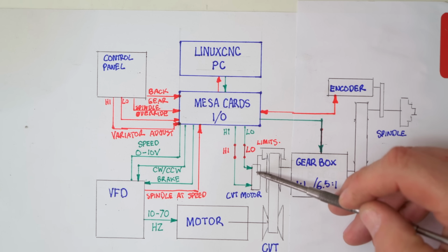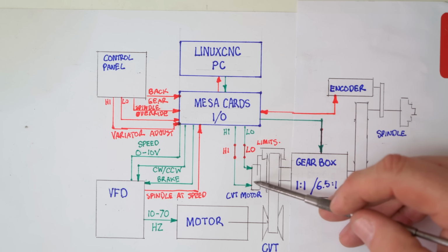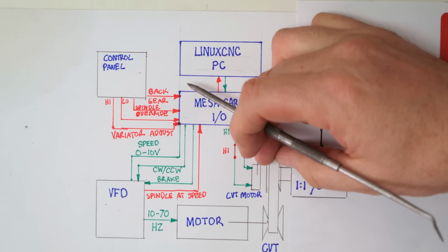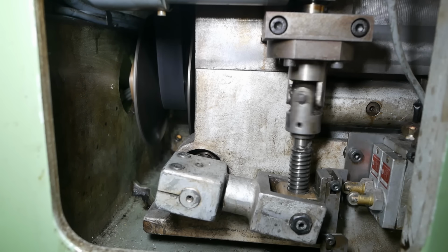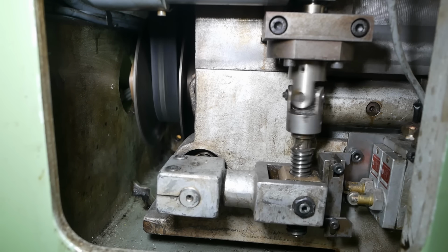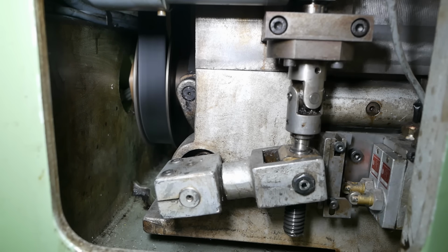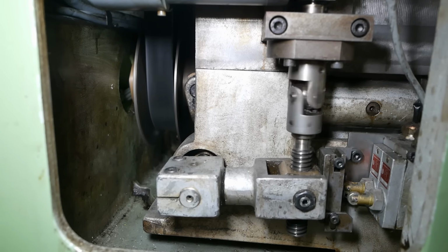Unfortunately, this three-phase motor, which turns at constant speed, is driving some gearing to squeeze it together or open it. It takes about 5 seconds to go from the lowest possible ratio to the highest possible ratio. However, the change in reduction ratio is not linear over those 5 seconds.